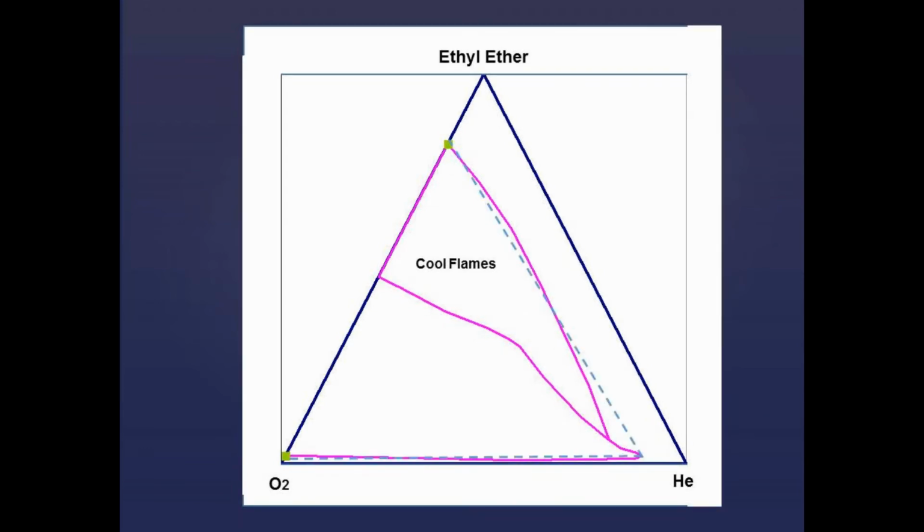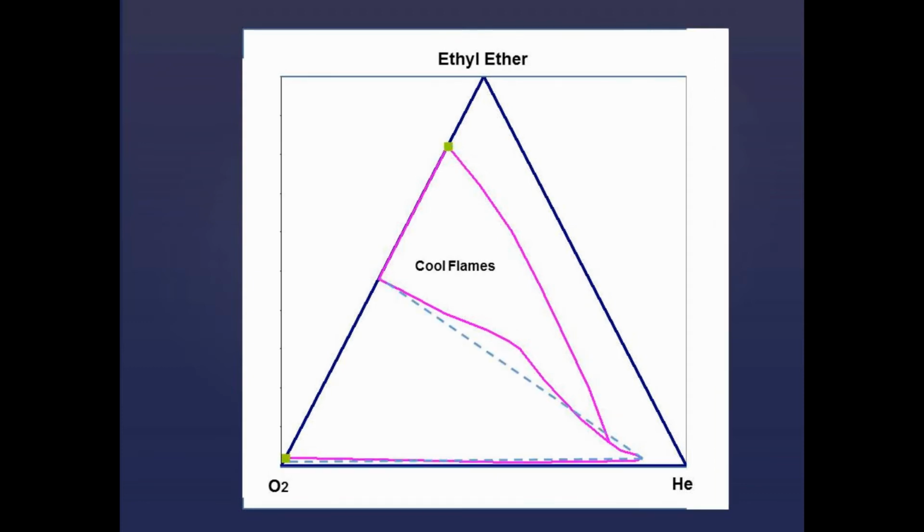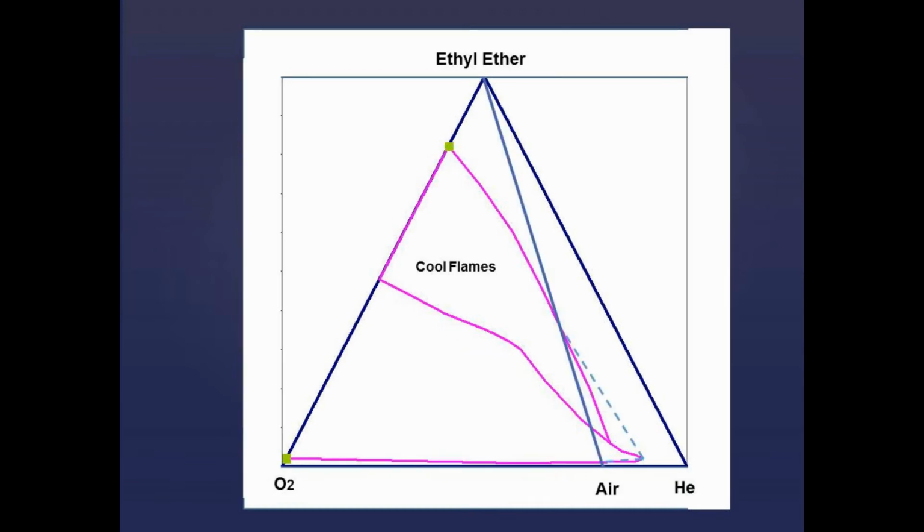Although the min oxygen data point is not published, we can take it as being near the nose of the curve, and the dotted lines show how a constructed fire limit diagram would look that might be less than ideal for practical use. If we wanted to focus on the intense combustion region, the constructed triangle for that region would be an even less good fit. And if we were focusing on just the ethyl ether air helium region, the constructed triangle would be a much less good fit.